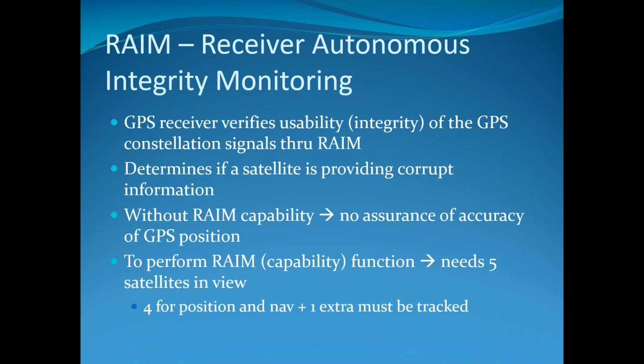If not, it'll give us a RAIM alert to tell us that we cannot use GPS or any satellite-based technology on that flight. Now it almost never comes back not having at least 5. It's really rare to have a RAIM check fail. But every time you send a dispatch release, it does what's called a RAIM check. And the RAIM check basically checks the route to make sure that we'll always have 5 or more satellites in view during the entire flight. And as long as that's okay, it'll come back as saying RAIM check passed, and that means that for that flight we're okay to use any type of satellite-based technology.